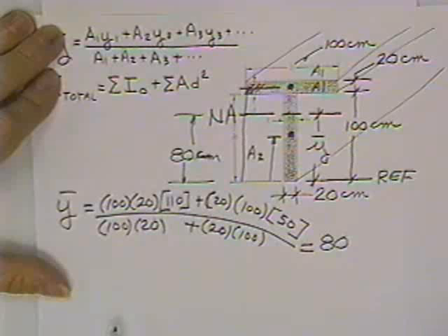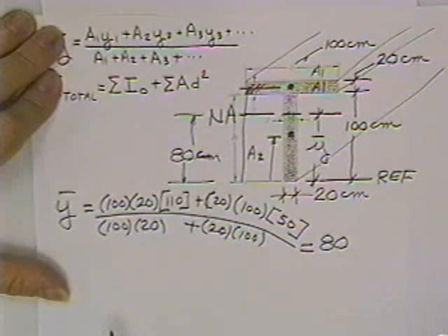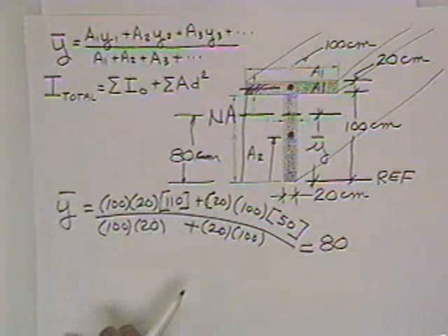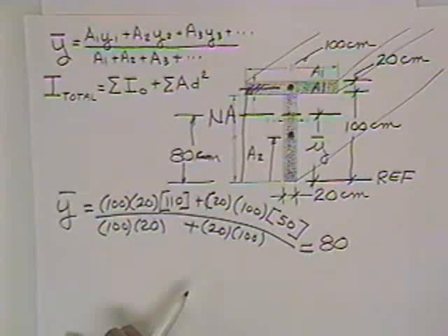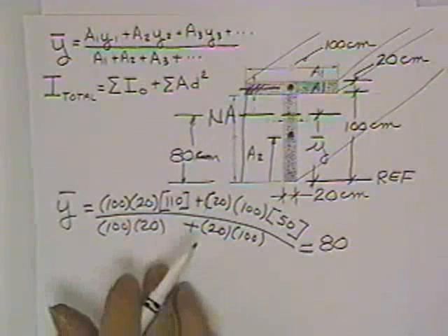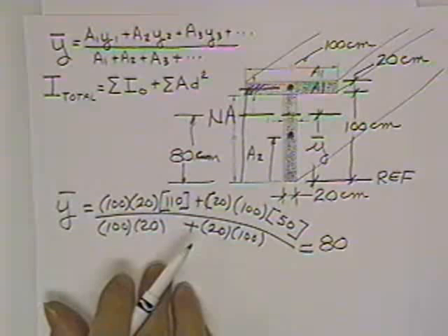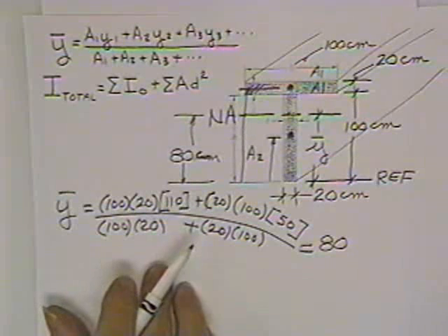Now, all areas have a moment of inertia just because they're there. All they got to do is just be. The list of the magnitudes of those moments of inertia in your reference manual are on page 25, 26, around in there. They will give you moments of inertia about some rather strange axes, but the only ones you really need when you talk about bending of beams is I about the centroid, and that'll be shown in the book as I sub xc.